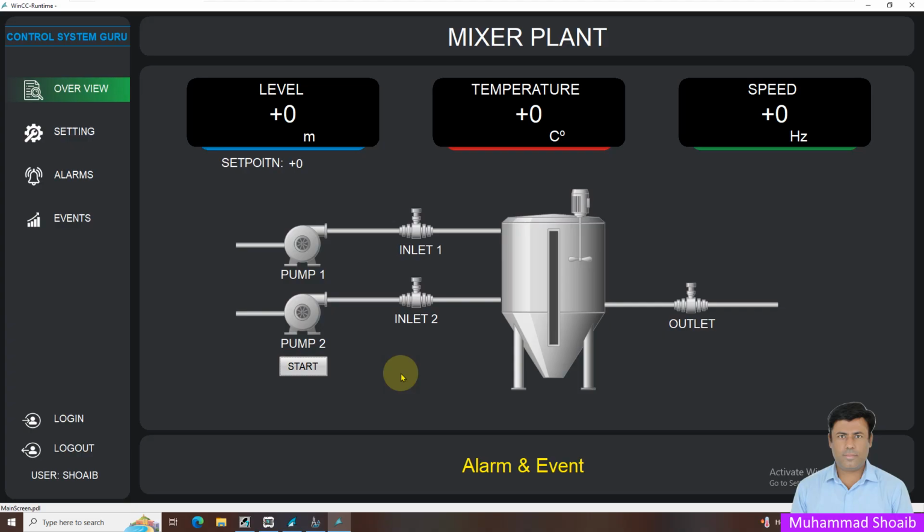In some cases, the RTU is very far away, like when we work over telemetry for a long distance over 4G, MPLS, broadband, or any other source. Because the distance is greater, a short or momentary pulse is not a workable solution.